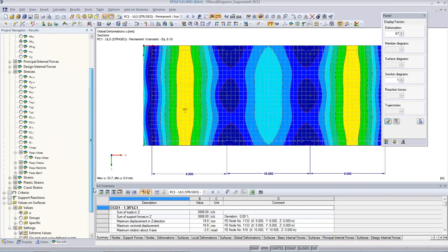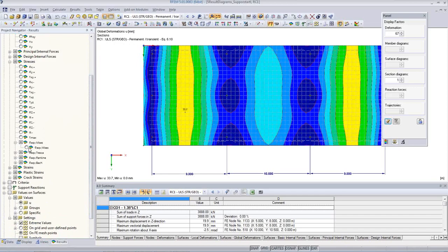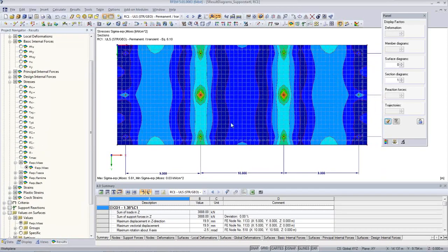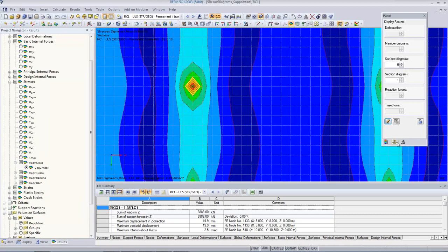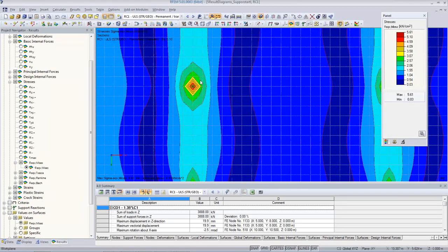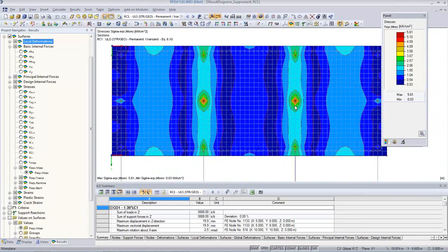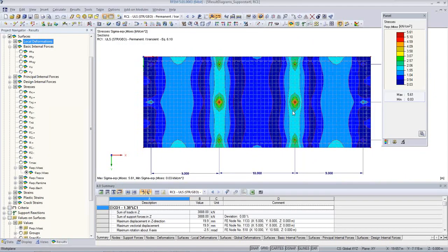And if I take a look at the maybe equivalent stress or forces, then you see here everything. There's high concentrations of stresses actually here on those points. So first of all, how to find singular points, how to find problematic points.